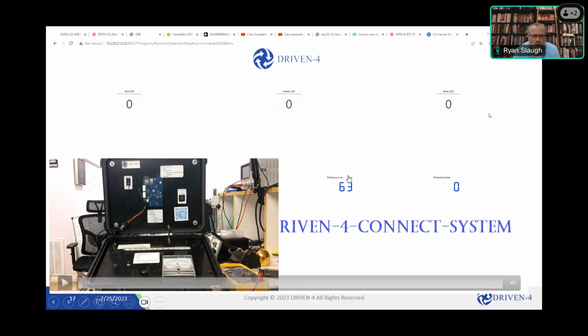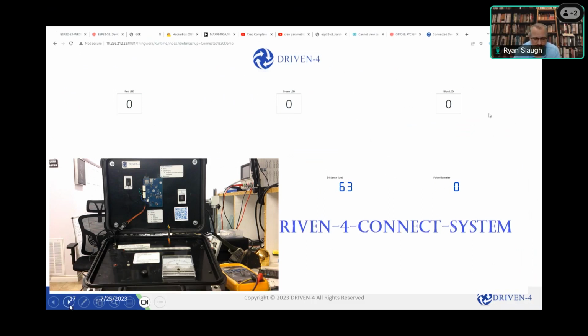Here again, we're taking analog inputs, analog outputs, digital inputs, digital outputs, and I2C. There's about 15 more ports available. We could do RS-232, 485, 4 to 20 milliamp sensors, runs the gamut of different sensors that you can put on this device, and all in a low power consumption package. It's got an onboard SD card that you can log data to if you need to, and of course the SIM card for use with the cellular when you have that.